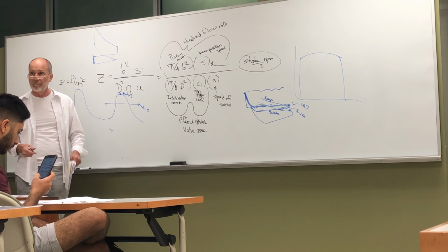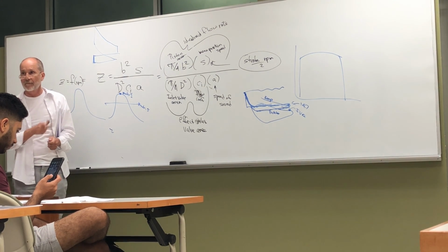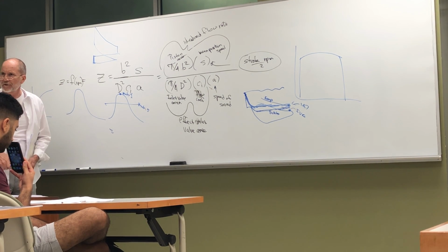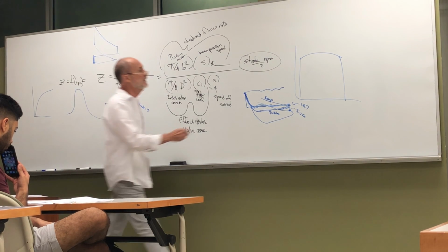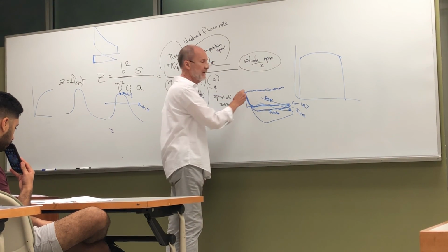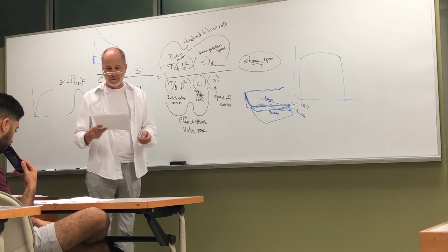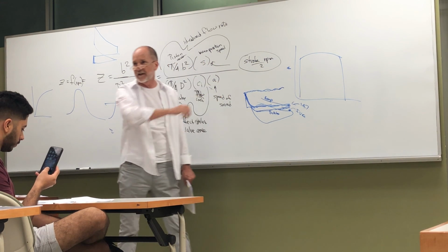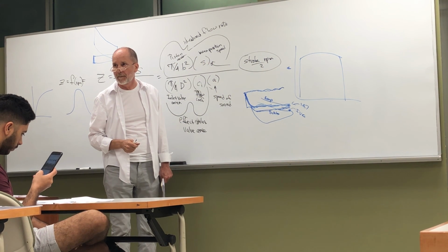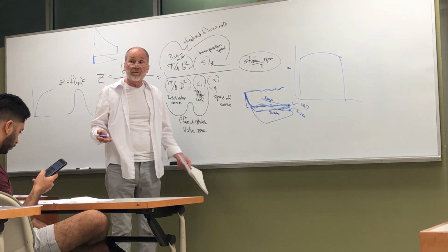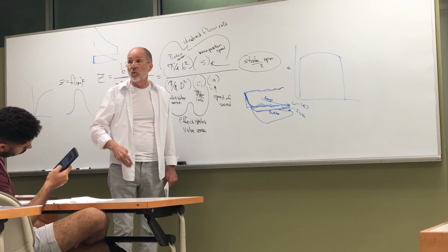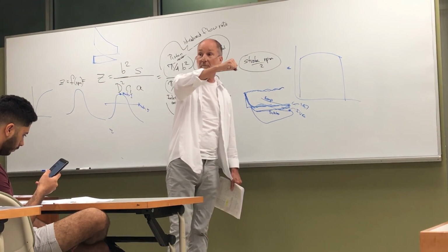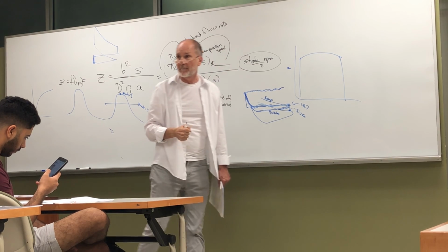But I'm still wondering, why is the exhaust valve opening at 20 psi in that picture? Okay, we're not talking about the exhaust valve now. What's that top line? Here the top line is the exhaust stroke. But that's above 14.7. Yeah, but the exhaust valve opens way over here somewhere. But why is it still above 14.7? Because when you open the exhaust valve, you're way above atmospheric pressure. You get down to atmospheric pressure, then the piston pushes the rest out at approximately atmospheric pressure.